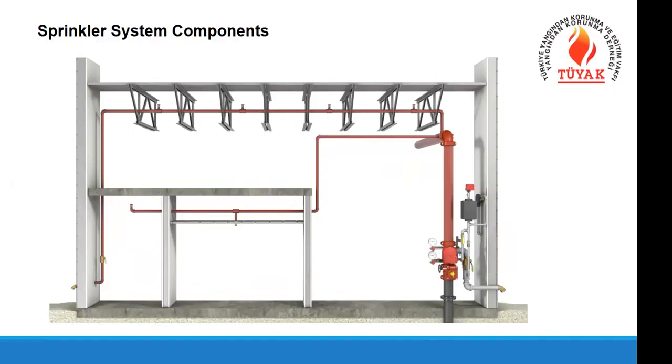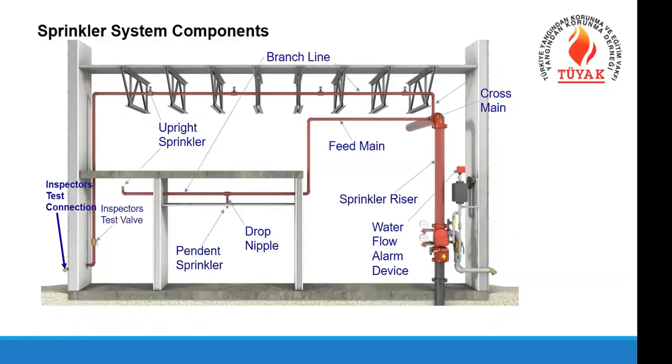have an alarm valve. Why do we call it an alarm valve? This is a water flow alarm device. When water flows through this device, it gives a mechanical or electrical alarm. So when a sprinkler operates inside the building, you get a signal, electrically or mechanically sounding an alarm to tell you there is a fire in the building. Everyone can evacuate and the fire brigade comes. So this system works as an alarm system as well, without any detectors; the sprinklers are the detectors for the fire.